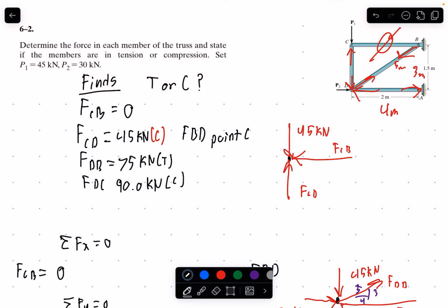Okay, so you have to really be careful whether these rods are in tension or compression right here. There's no shear forces, no bending moment acting for these. And really the main benefit of a truss system is since the loading is only tension or compression, we can take materials that are generally weaker in the shear direction and only load them in tension or compression.